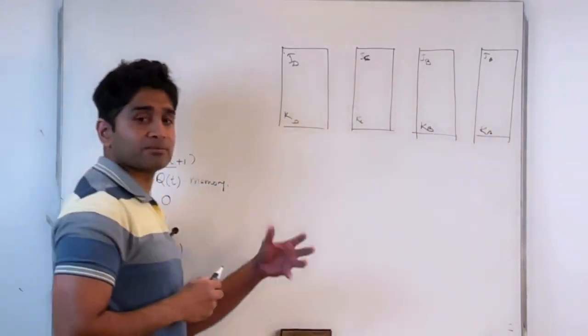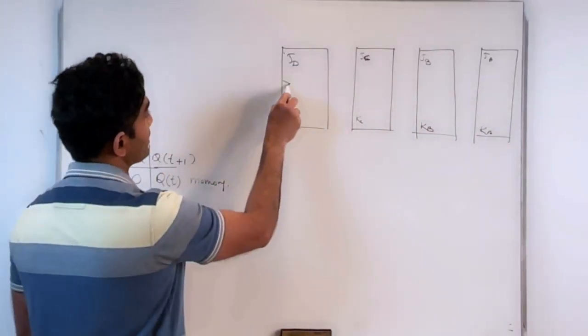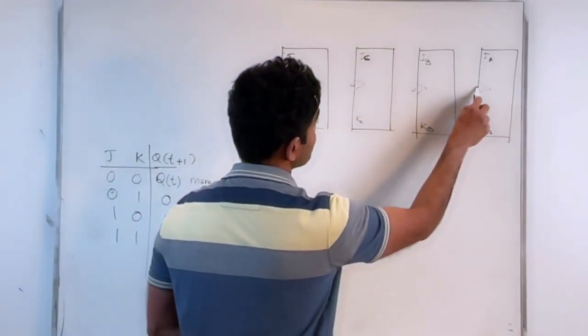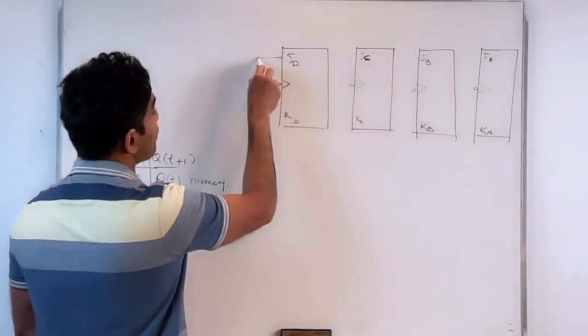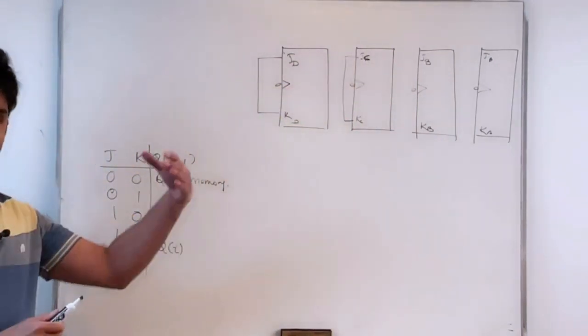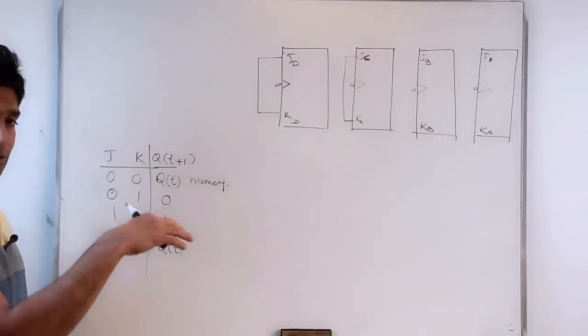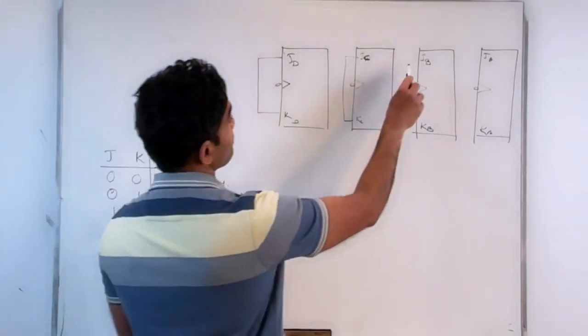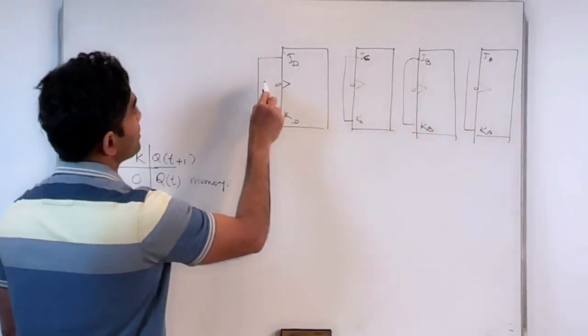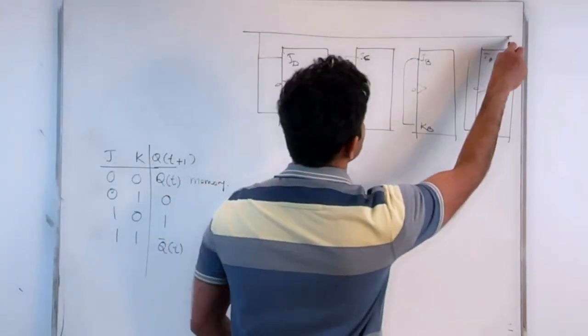The way we designed the counter, again, we assume that we have designed them using these negative edge triggered flip-flops. We configured each of the flip-flops in the toggle state. That means the output toggles with every new clock pulse, goes from 1 to 0, 0 to 1 with every clock pulse. We know what the toggle state is.